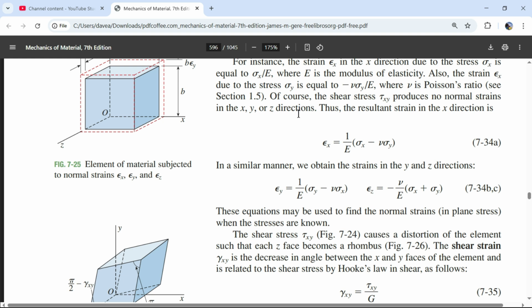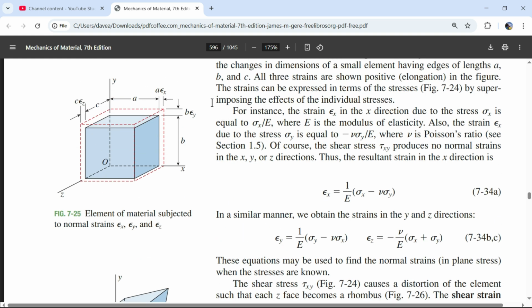All right, sweet. We're still dealing with plane stress, so we have no sigma z, and that's not going to cause anything in this. When we're talking triaxial stress, now I get that. If we have stresses in 3 directions, we're going to pick up another value, and that value is going to be pretty easy. If we have positive z, we're going to shrink in this x direction. So we would have a negative v sigma z. Hell yeah, that's cool.